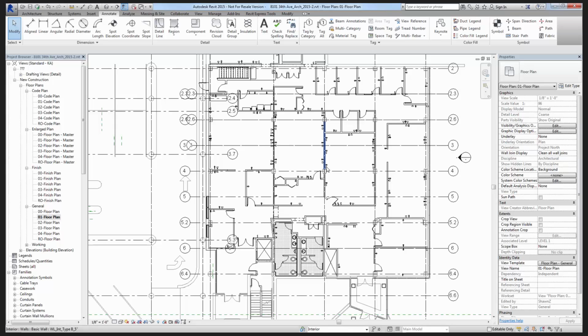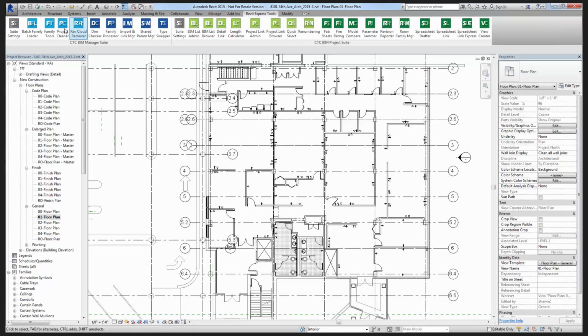And finally, the last step here again was using a tool like BIMlist. This project here has almost none of the content that I would normally use other than what I transferred in using the batch family loader. So instead of users having to constantly go out and load content and browsing for content in the library, which gets very frustrating, what I can do is let them use something like a BIMlist browser. And if I have my library set up properly for them, they should be able to find any content that they need and start leveraging that to bring content into their project. Apparently mine is a remote database and is doing an update right now. But they can go through the process of dragging content in as they need it, which makes that loading process much more streamlined and much easier during a project takeover.